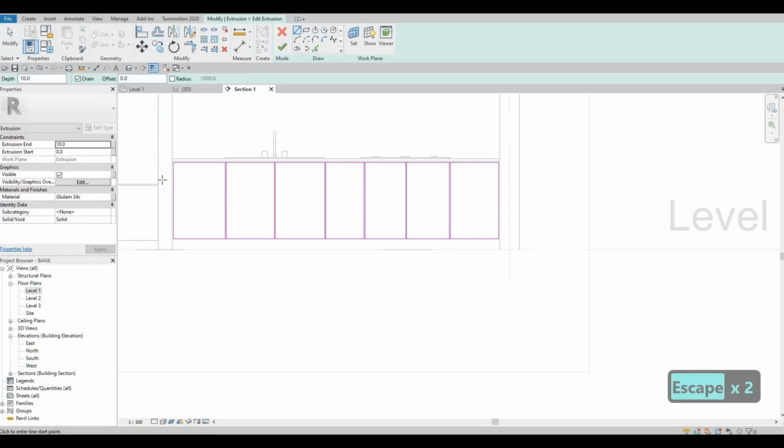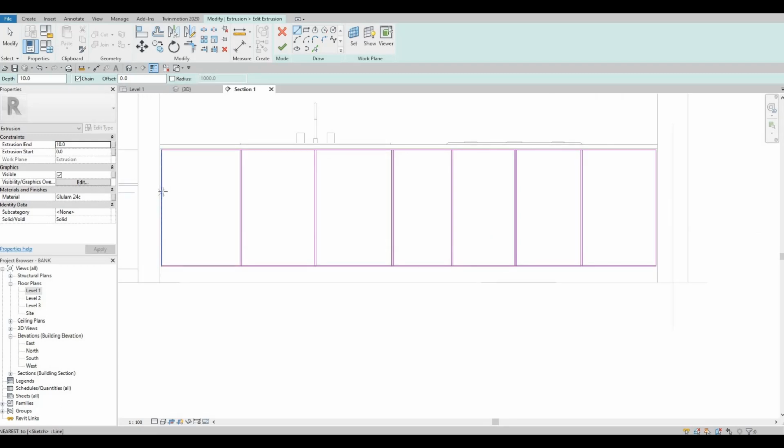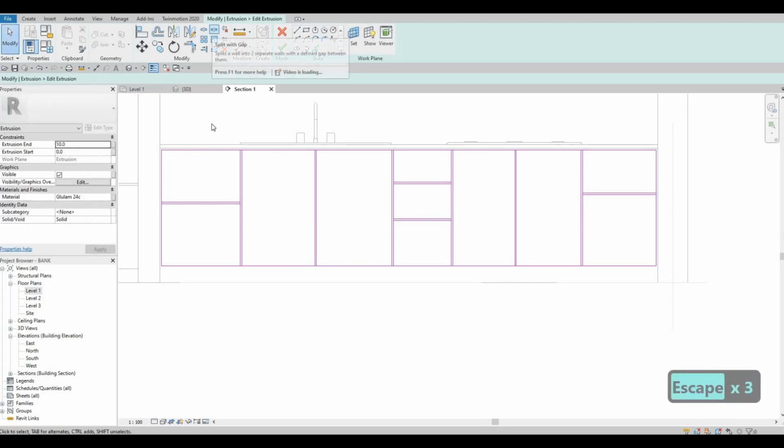We're going to have something, for example, here I want drawers, here I want probably drawers as well, so double, and then here I want something at the top only. So different kinds of drawers. We could click on pick line and then offset that to 10 as well. So we're creating those gaps in order for us to slice them, so split element them.